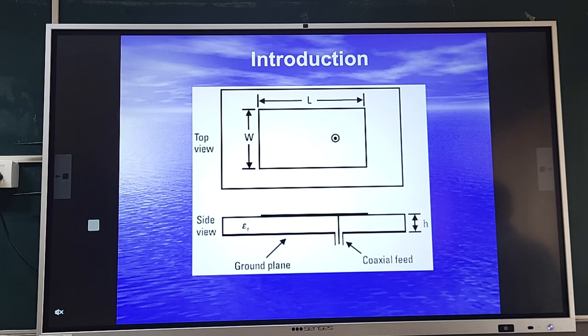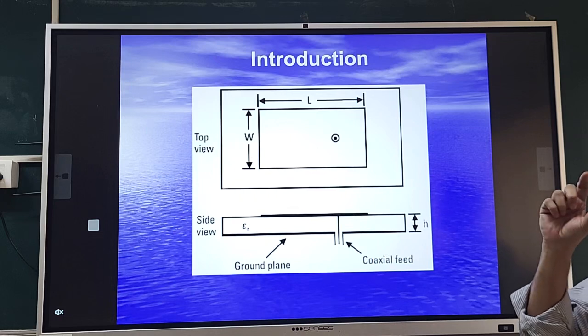Now, what are the different substrates which are available? As I mentioned, I have FR4. That is a very cheap substrate but very lossy. For a low-cost solution, that is the one we use. In fact, for all lab design purposes, we use the FR4 substrate. Another substrate is RT Duroid. The dielectric constant is 2.33 and tan delta is 0.002, or 0.001; that range is always given. The substrate thickness comes in different variations. I can have a 1/16 inch substrate, or a 1/32 inch substrate. Generally we use an FR4 substrate or RT Duroid with a substrate thickness of 1.6 mm.